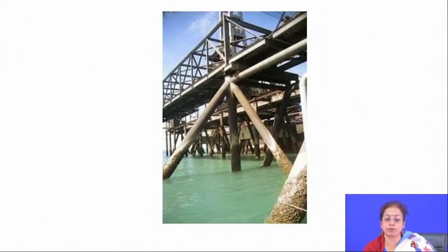Similarly, this is the case for bridges. Bridges are usually connected to magnesium pieces as anodes at regular intervals by typical wire. Whenever the magnesium anodes are there all throughout the bridge at regular intervals, corrosion happens in the magnesium in contrast to your steel. So, your steel structure is protected.